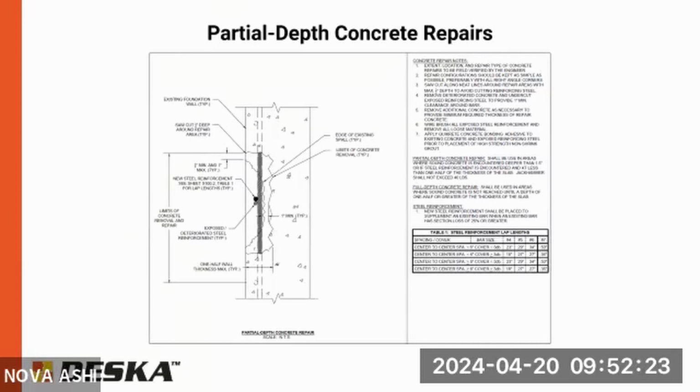So if it's a structural slab, then yes. If it's a slab on grade, basement foundation, you might have some welded wire mesh in there. It's not typically enough to cause a lot of damage. But if it's a floating slab, or let's say you have a garage slab that has a room below it, then that would be a structural slab. And yeah, if it's, let's say, an open court setup where it's open to the elements and water is able to get in there and cause damage, then yeah.